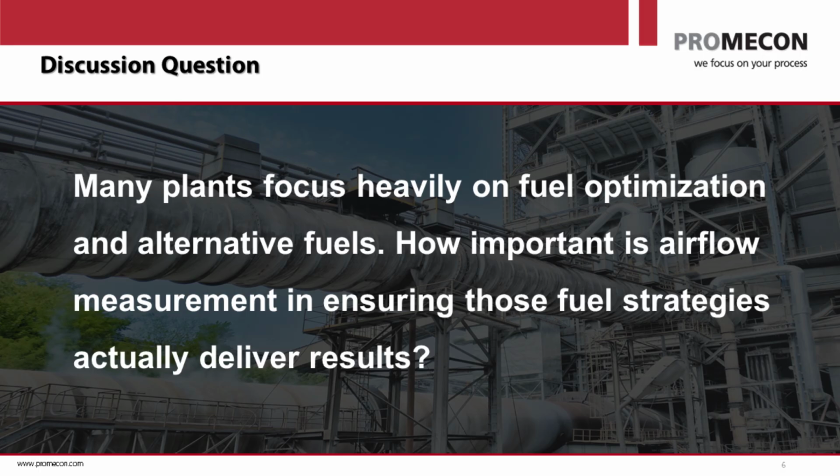One example would be the Downcomer, where traditionally the measured oxygen would be the set point. But this is also not optimal. Airflow should be the set point with a correction in a cascaded control loop.